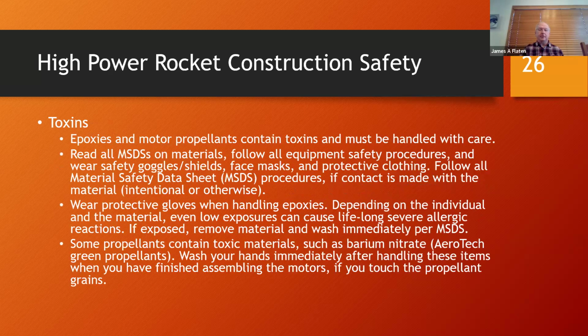Some of the epoxies that you'll use and some of the propellants associated with the motors are actually toxic. So make sure you're familiar with the material safety data sheets for the materials that you're using and follow the procedures, including ventilation, protective gloves and other things. And if you happen to touch these things or be exposed to them, follow the material safety data sheet as far as how to deal with that, including washing up, including seeking medical attention if that's appropriate.